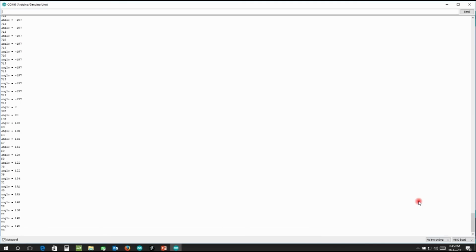So this way you can map a particular potential or rotation to the corresponding voltage or degrees, and there are a lot of codes and sensors available for the Arduino platform. You can use them, learn the code, and these are beneficial when you want to acquire data from small UAV aircraft, or some platform where you want to analyze how it's behaving, what its turn rate is, what its pitching angle is. So this will be beneficial for you.